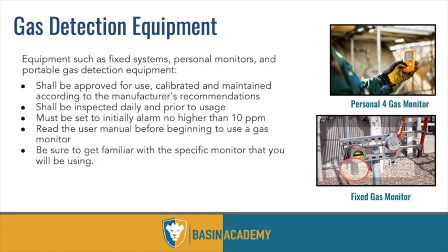There's different gas detection equipment out there that we use for surveying facilities. Some of them are permanent, some of them are mobile, some of them are just remote area monitoring, and they're used in different instances for different reasons, but they do need to be calibrated and maintained properly. They should be bump tested and inspected before use each day.